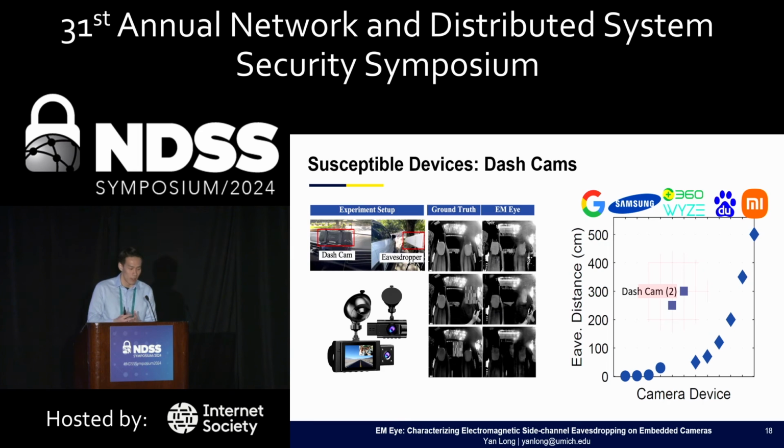We found that different cameras have different best frequencies because of the different layouts and cable lengths. You also get gigahertz frequencies, and we found that at long distances, higher frequencies probably work best. That's our experience. Was it always harmonics of the clock, or was that number just random? It's mostly the harmonics of the clock frequency, because I think the data rate is twice the clock frequency. They're doing overclocking in the protocol. Yeah. Thank you.